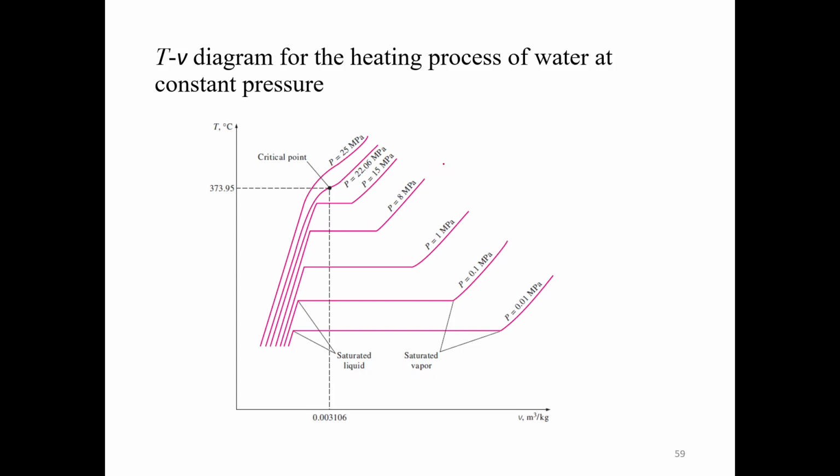Now if we start from here, let's say we start from this side and come in this way. We have a certain pressure and we are reducing the volume. By reducing the volume we can convert that gas. What we have is a superheated region, that means a gas, and you can convert that gas into a liquid while you are compressing it and reducing the volume, right?